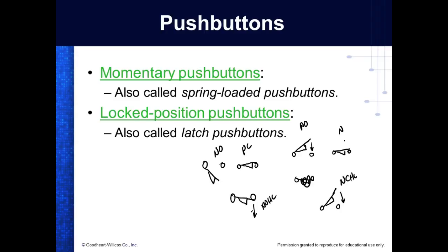Now what we do on these is we draw these symbols like the machine is when it's at rest or at reset. So if I've got a big carriage out there and I'm trying to sense where it's left and right, and we always park it on the left, and it's got a normally open switch, then when we draw our diagram, it would be a normally open, held closed, right? That makes sense. So that's why we have these different symbols, so we can show what that limit switch is when the equipment is at rest.